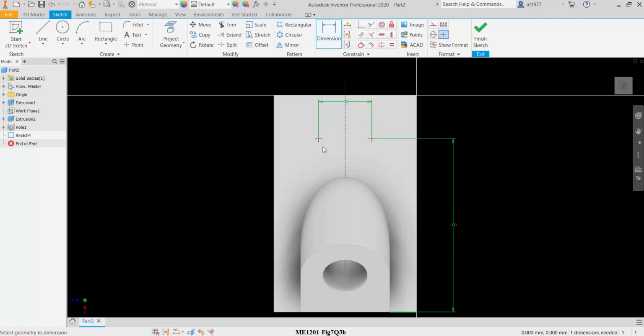If you find that this point is not in line with the other point, what you need to do is create a constraint between them. Either make both points horizontal, in this case should be horizontal, or in this case vertical. Just click on these 2 points and they become horizontal. But in this case I do not need them, because notice that my 2 points are now purple, meaning that they are constrained.